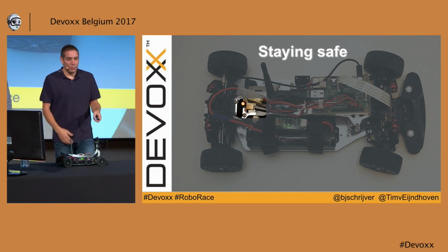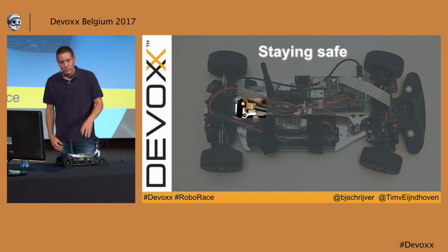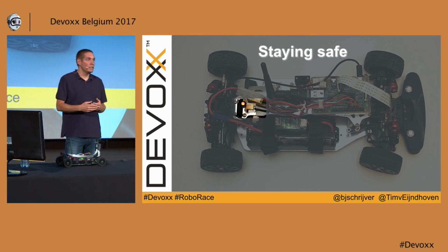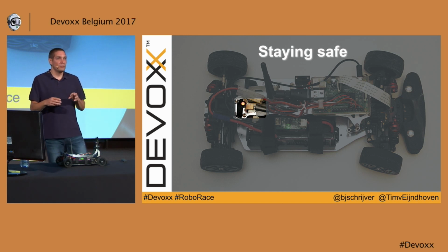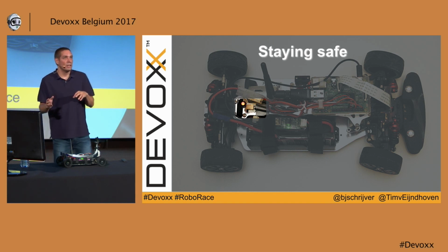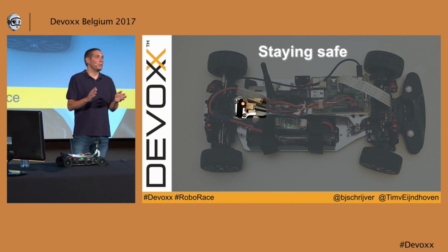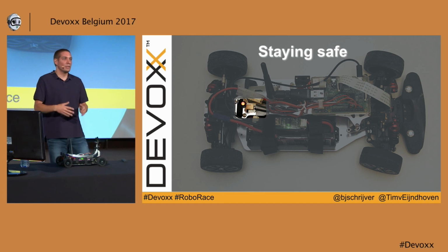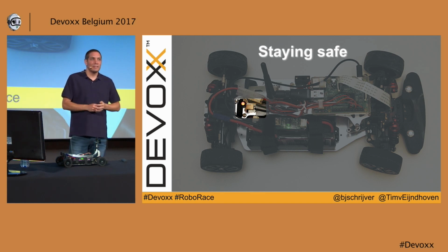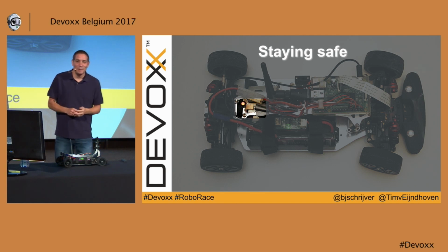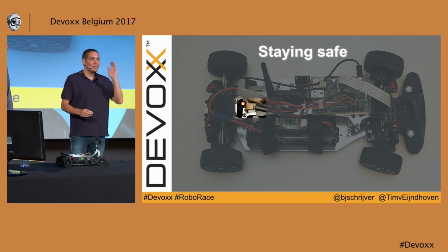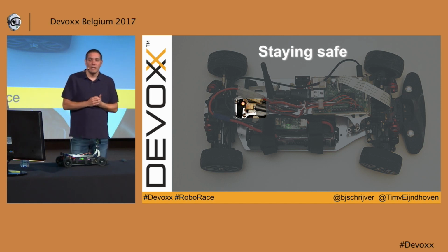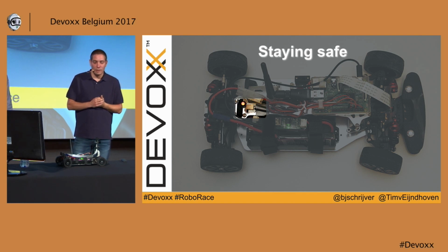And so then our first prototype was, we had the Raspberry Pi, Servo Blaster on there. We would have a Wi-Fi connection to the Pi with a laptop, log in over SSH, and then we were just typing echo 0 is 250 to dev Servo Blaster. And then it would start driving, and it wouldn't stop anymore. So then we would type echo something quick that would make it go left, and echo something else, go to the right, and echo something else, and it would stop. And we really quickly noticed that this approach didn't really scale. Because we ended up running most of the time, running after the car to go fetch it. And we have a fairly large hall next to our office, and this is where we really need to exercise